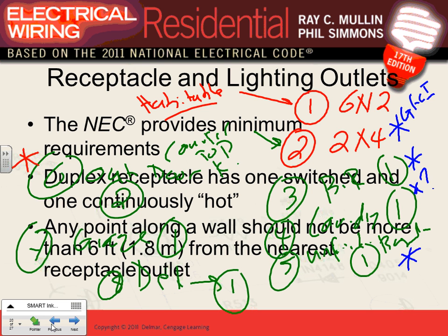Okay, let's talk about unfinished basement. GFCI. Let's talk about outdoor. Of course, yeah, GFCI. You need one for an unfinished basement? Yes, at least one receptacle for unfinished basement. Garage. GFCI? Yeah. GFCI. Deck. Yeah. Deck area, GFCI.